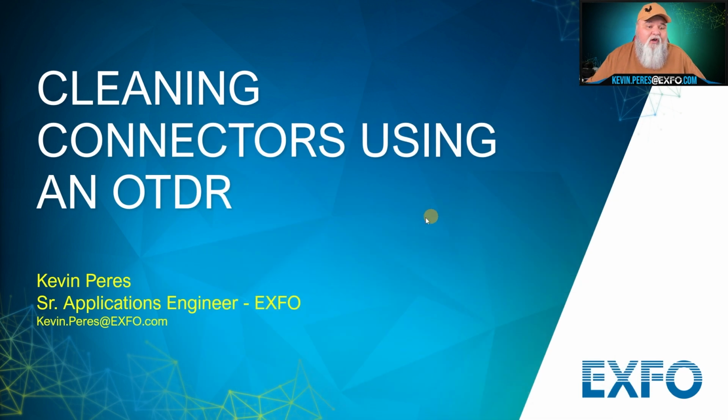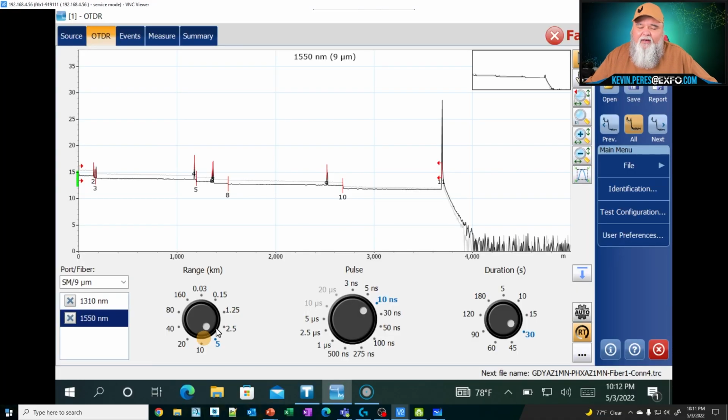I'm going to go ahead and do a quick OTDR shot. I do a whole session on OTDRs, so I'm not going to get into the setups too much. But here's what we're going to do. I shot a quick trace. If I'm troubleshooting connectors, or troubleshooting at all, I want to use longer durations and a shorter pulse width. I want my duration to be fairly long, and my pulse width as short as I can possibly get it, and still get a nice clean trace. As I increase my duration, I can decrease my pulse width. That's essentially what I'm looking to do.